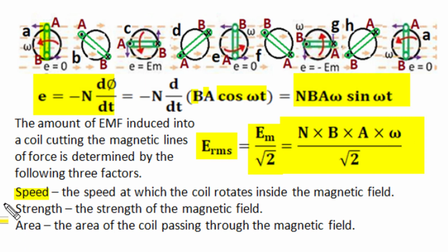It depends upon the strength of the working magnetic field around this rotating loop. The higher the strength of the magnetic field, the higher the flux linkages with the given area of the rectangle loop, and the higher the rate of change of flux linkages. So induced EMF is directly proportional to the strength of magnetic induction. It is also directly proportional to the number of turns in the rectangle loop.